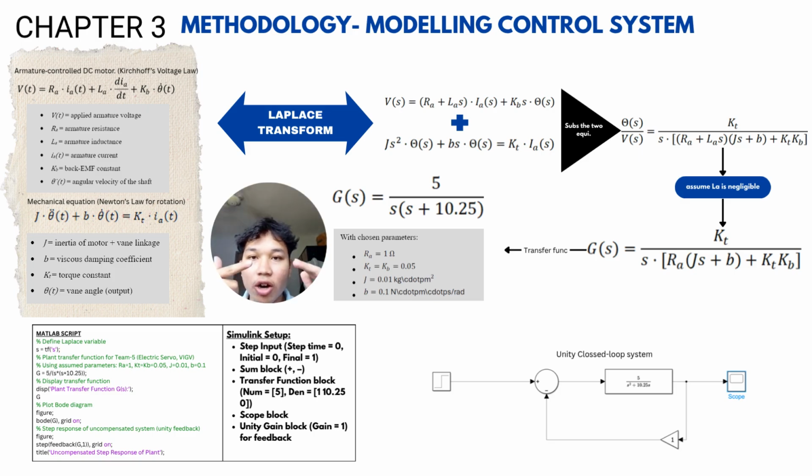Second is Newton's law of rotation, which describes the mechanical side, how torque turns the motor shaft while battling heavy inertia and friction. Now, raw physics gives us calculus with time derivatives, which is very hard to solve directly. So we use a tool called the Laplace transform. Think of it as a translator. It turns hard calculus into simple high school algebra by moving us from the time domain to the frequency domain.